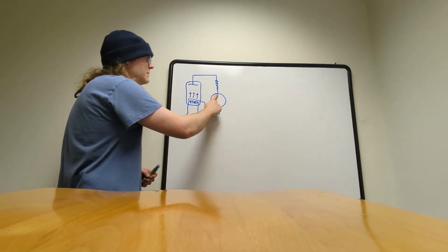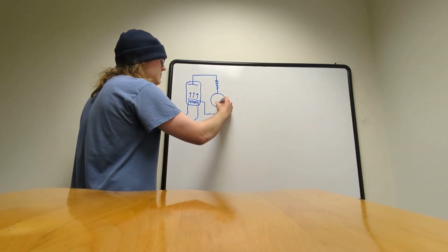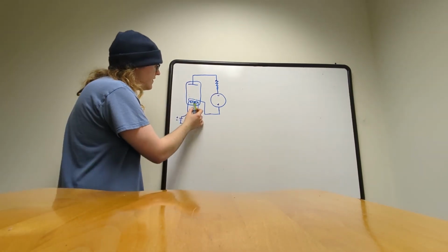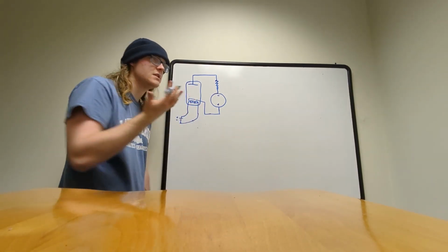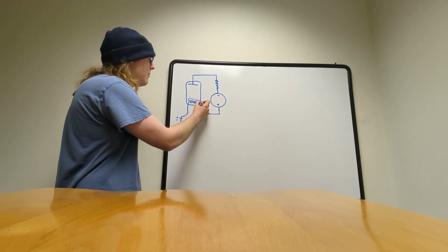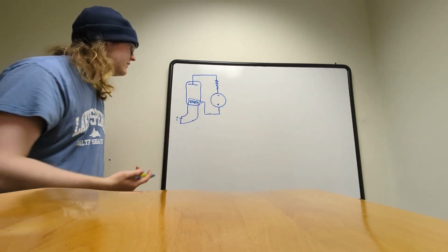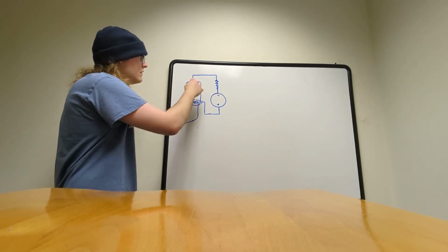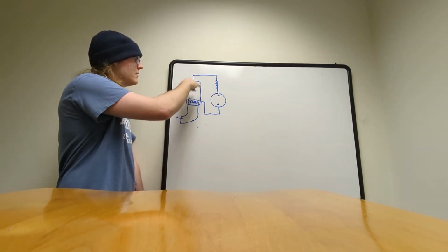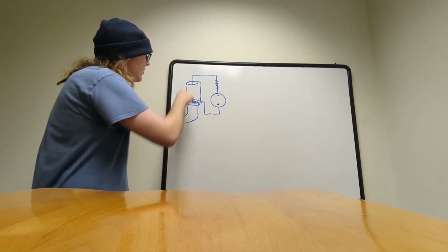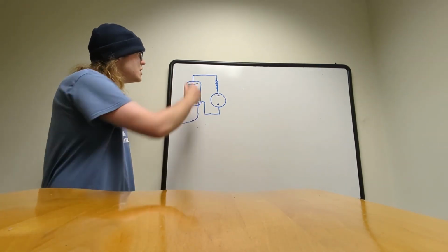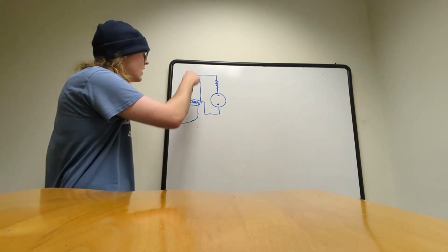Now, when we flip this voltage source, and instead make this positive and make this negative, a unique situation occurs. So this heated tungsten filament on top here now has a positive voltage as opposed to a negative voltage. Well, what does this mean? If this were negatively charged, we would expect the electrons to be emitted from this side and flow to this side, but that's not the case. Because this side is not heated as opposed to this side, no thermionic emission will occur, and no circuit will be completed by the flow of electrons across this vacuum gap.